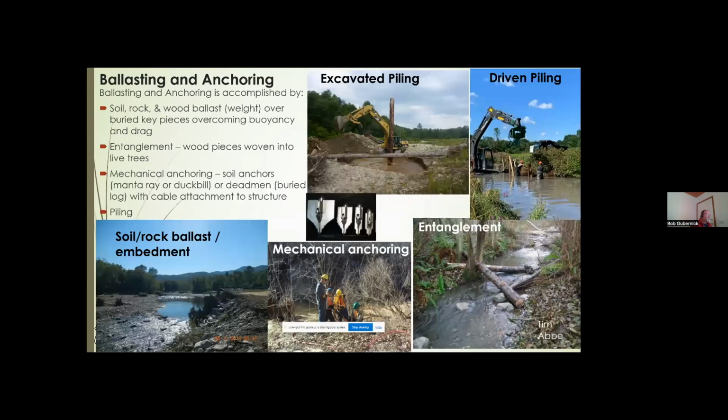So in order to keep those down, you have to have ballast, some anchoring methodology. There's lots of ways to structures. You can embed them, where you will essentially dig a trench and place the log in there and put the material over top, and there's enough material on the top to overcome the buoyancy of the wood and keep the wood in place.